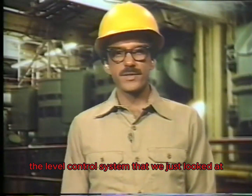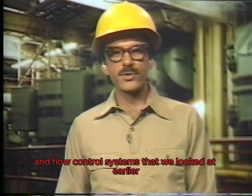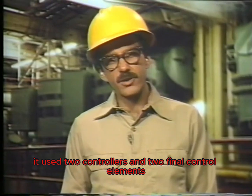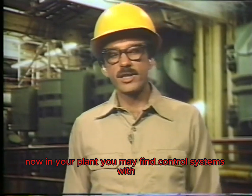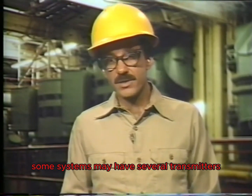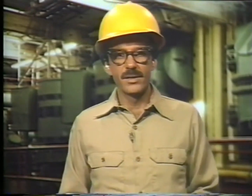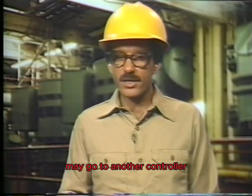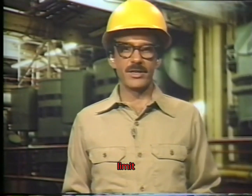The level control system that we just looked at was different from the basic temperature, pressure, and flow control systems that we looked at earlier. It used two controllers and two final control elements in order to maintain level. Now, in your plant, you may find control systems with any number of combinations of instruments. Some systems may have several transmitters sending signals to one or more controllers. Or you may find a system where the output from one controller may go to another controller. The variety of pneumatic control systems is almost limitless.